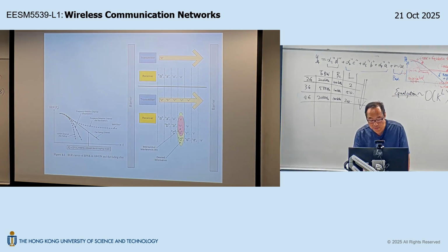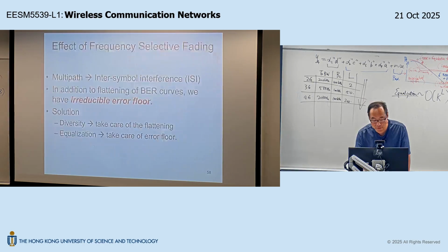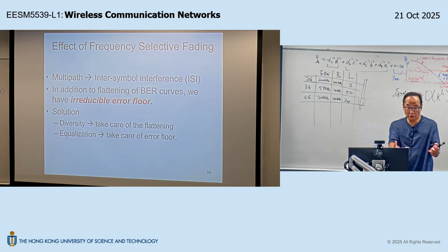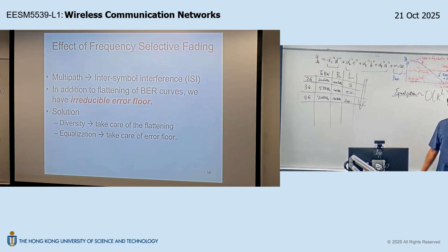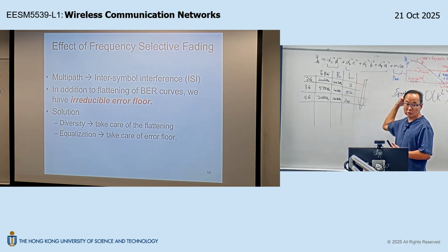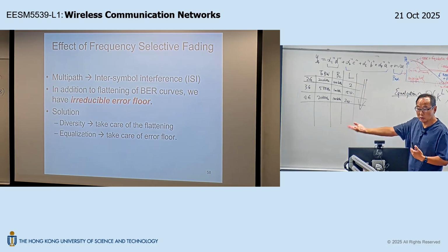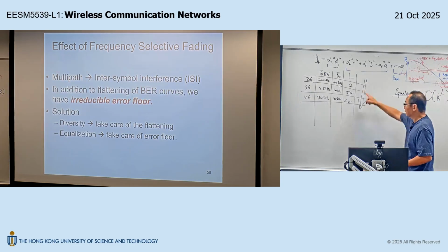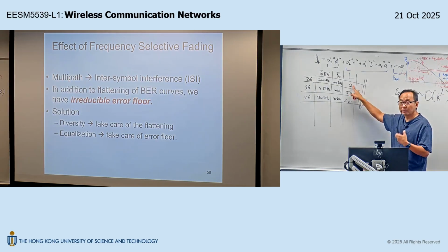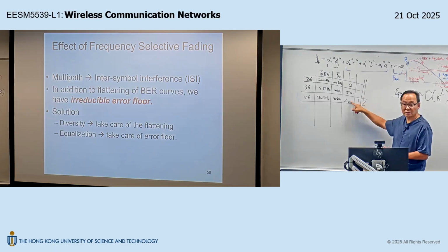And as I said, the problem is, we know the solution roadmap is equalization, but brute force equalization, that is, if you dump all the burden of the equalization on the receiver, has an exponential complexity, which is not scalable. So this brute force equalization at the receiver may work for GSM, and indeed there is an equalizer on every GSM mobile receiver. Okay? But GSM just needs to deal with 2 resolvable symbols. But the same brute force equalization method in GSM cannot be used to deal with these cases, right?